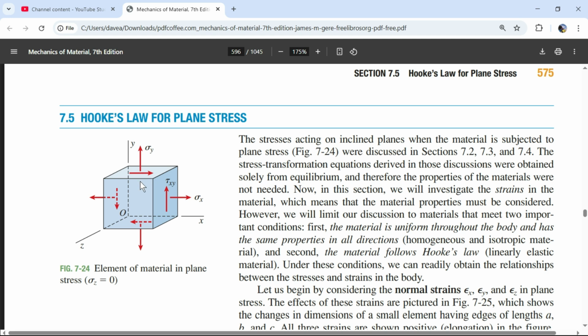And then sure, if you cut down into this beam a little bit, well, then I can have some shear force here and shear force here. But if it doesn't exist at the very surface, then due to continuity, if I just go down just a little bit, there's still gonna be hardly any shear force here, hardly any here. So these will be hardly any because it'll be approaching zero as it meets that face.